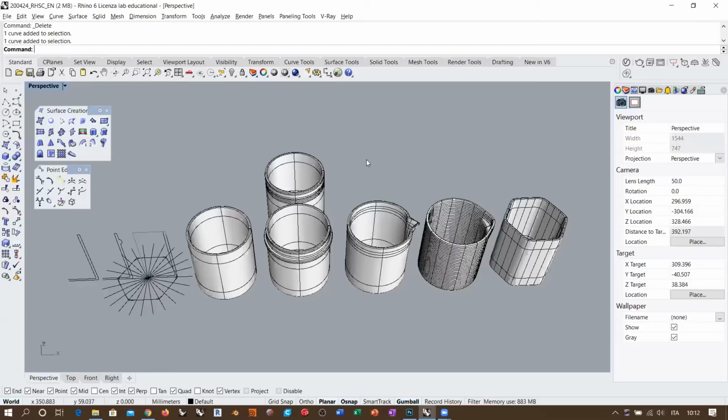When you talk about subdivision surfaces, you are normally talking about meshes. And in that case, for example, there is always this transition between the SubD object and the mesh object. And when you switch to a NURBS object, then normally you will have polysurfaces with all the consequences of having polysurfaces instead of one single surface. In terms of continuity, yes, it allows you to create very smooth sets of surfaces or very smooth meshes, actually.